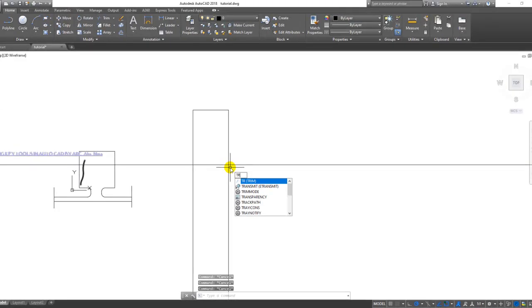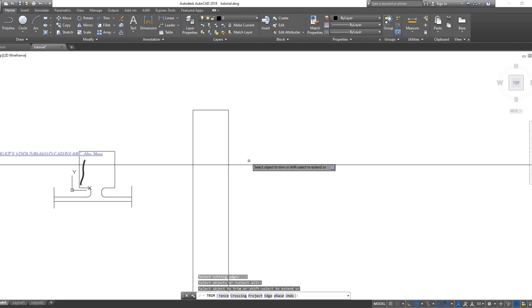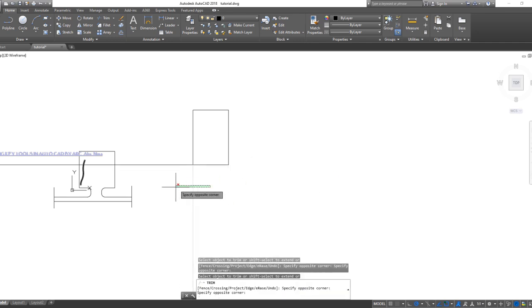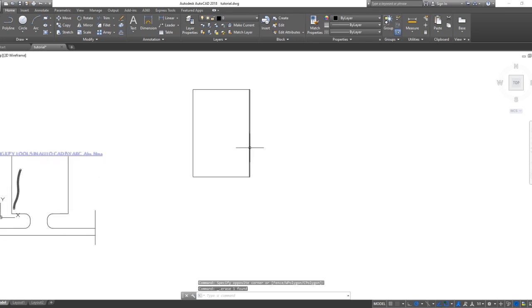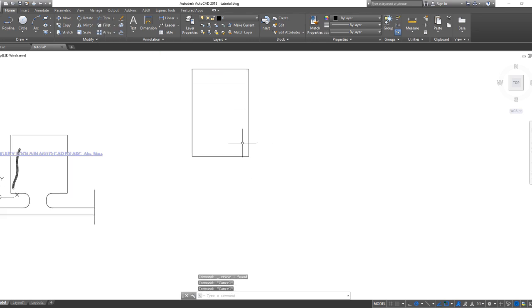Then you have to now enter twice. 1, 2. So you see, I'm trimming. So that is how you can use the trimming tool. So also the second tool there is the extend. So extend, let me say for instance, I'm offsetting through now, offset T. So I now want to extend these lines to join this one which I offset.